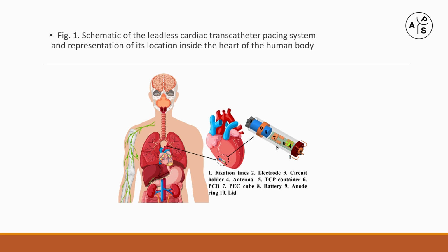Moreover, in case of misalignment with the antenna in the external monitoring system, if the antenna has CP radiation properties, it will be advantageous because it will mitigate the multipath interference as compared to linear polarization. So we targeted to design an ultra-compact circularly polarized multiband implantable antenna which can work well and fit easily into